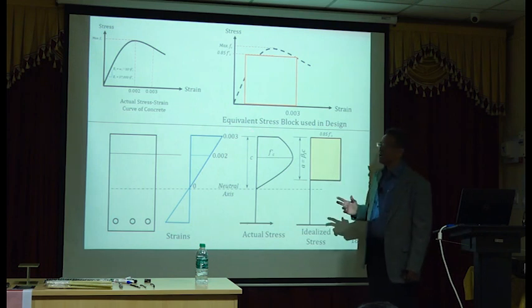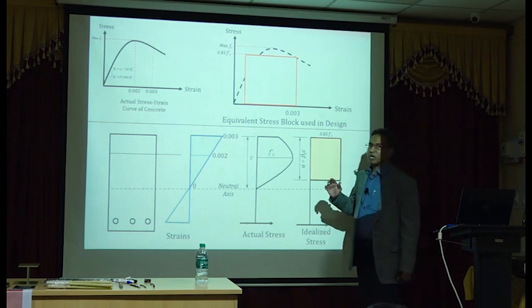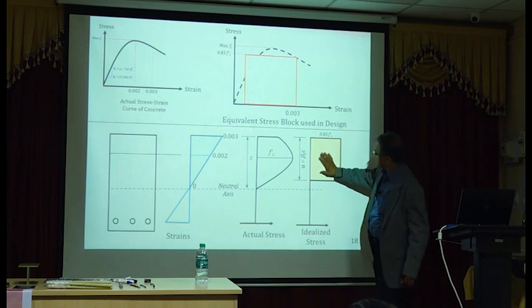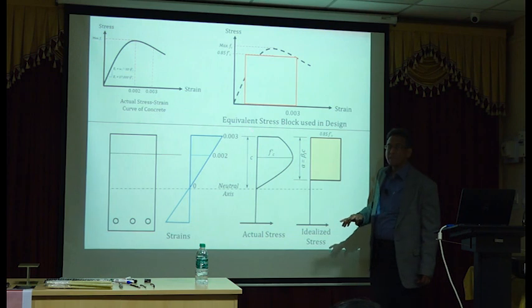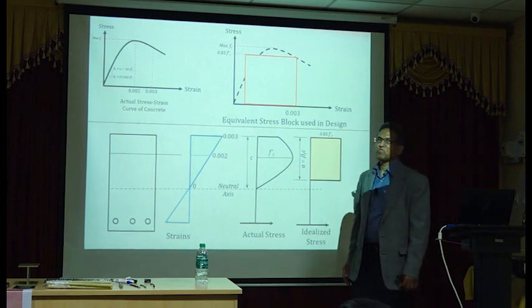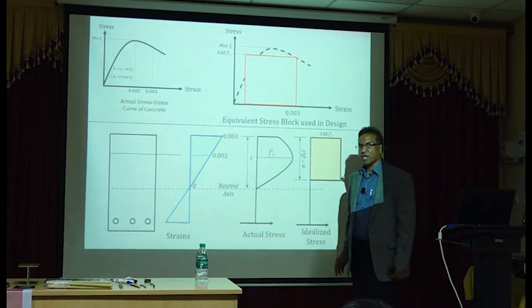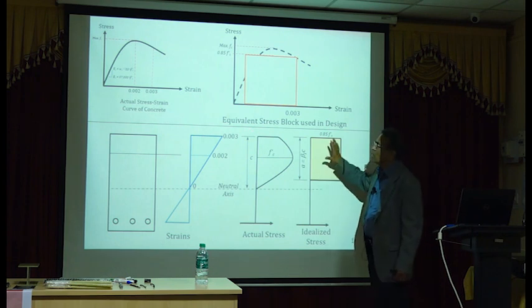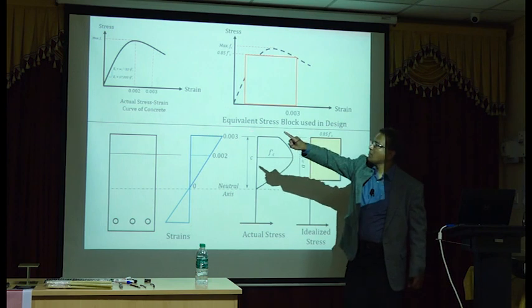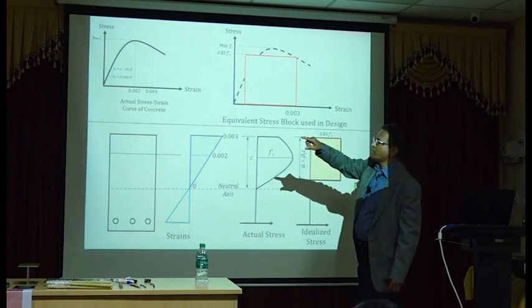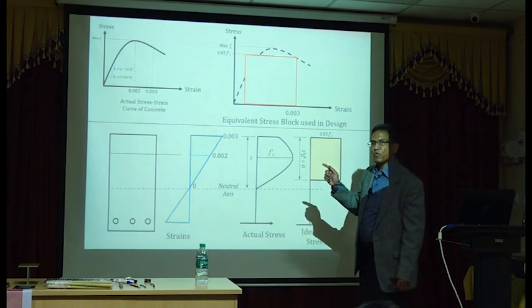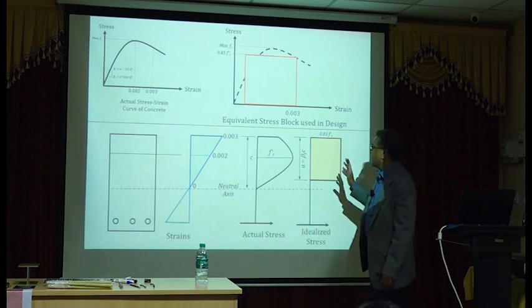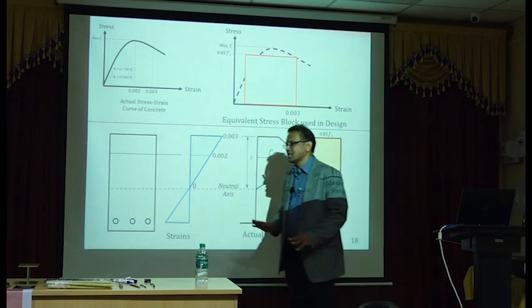And for higher strength concretes, it's smaller. That means this stress block will terminate here, 0.65 for 8000 psi concrete, which is about 55 MPa concrete. Okay? So these differences: this 0.85 F prime C and the IS 456 uses 0.444 FCK. What difference does that make?